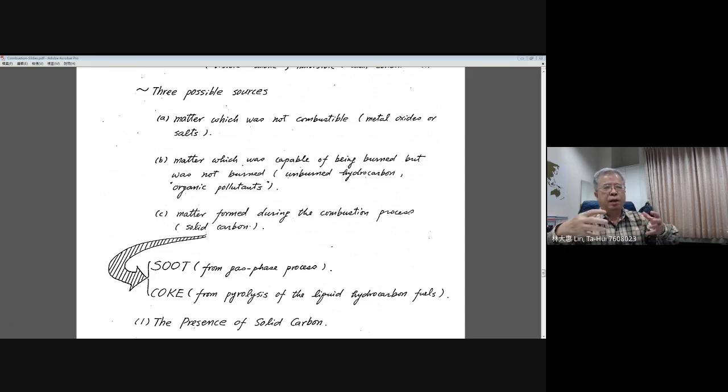This always occurs in the combustion chamber because when we talk about a combustion process for liquid fuel and for solid fuel, they always need a so-called initial process. For example, liquid fuel needs a certain time for evaporation to produce fuel vapor, then goes through gas phase combustion.